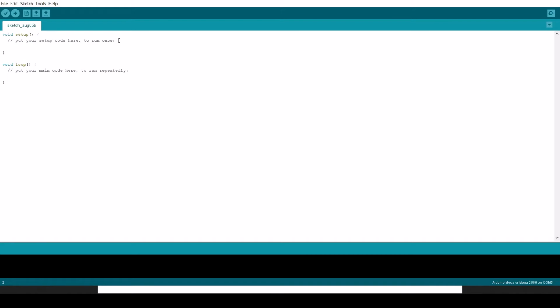So we want to write data to pin 13, right? We want to write voltage, set the voltage high. So we're sending power to pin 13. That will in turn send power to our LED, keeping it on. So how do we do that?